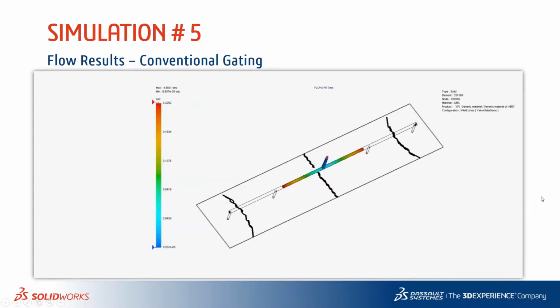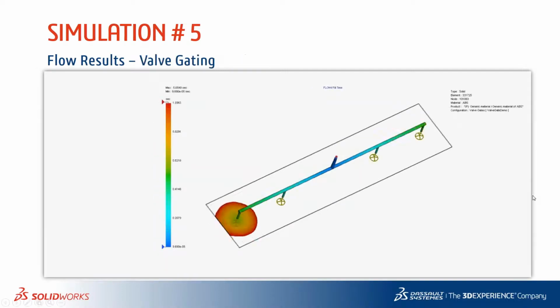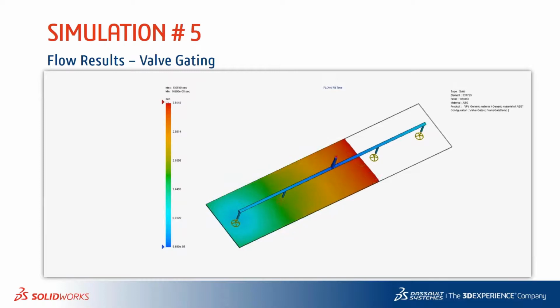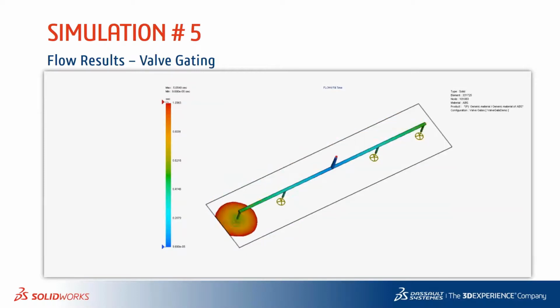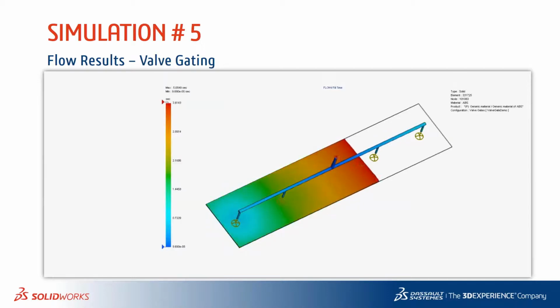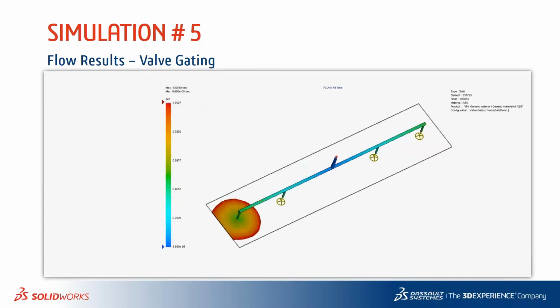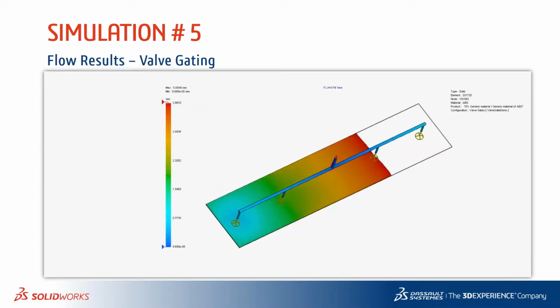Okay. So the natural way to address this type of issue, or how do we get rid of the weld lines, is we can have the same sort of runner system configuration, but we start valve gating it sequentially, open like an on and off condition of the valve gate. We sequence it automatically, and so you can see in this example using valve gating that we literally get rid of all the weld lines that we have seen before with the conventional gating system.